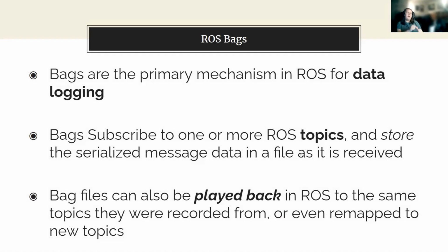Okay. The other thing with administration is ROS bags. These are very important if you're ever going to be doing anything with testing. This is how you data log in ROS. So what a ROS bag essentially is, it's like a pseudo node almost. And all it does is it subscribes to a ROS topic and it collects and logs every single message that is received on that topic. And then what you can do to it, number one, you could read it out, right? So if you just wanted to check some log data, you could go through it. But the real important thing is you can play it back into ROS.